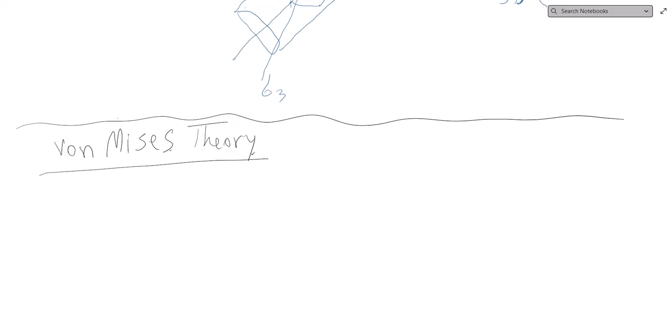Von Mises looks at the energy and considers the energy associated with distortion and deformation. When a material fails, there should be enough energy that deformation happens between the surfaces of the atomic crystal of the material, and that will cause the failure.